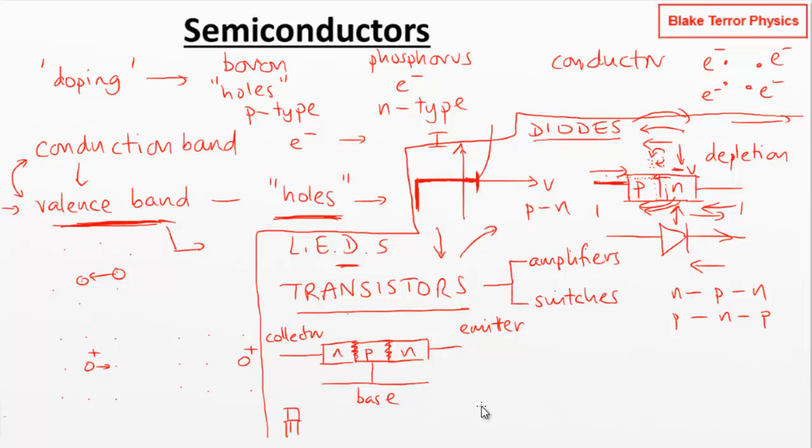So what is actually going on with all these bits then? Like I say, we've got these depletion zones at the boundaries, and as we saw with the diodes, these act as sort of insulating buffers when there's nothing else going on. So they're blocking current when things are just sitting around. But now we've got these different potential differences here. Okay, we've got a potential difference between collector and emitter, but we've also got a potential difference between collector and base, and then between base and emitter.